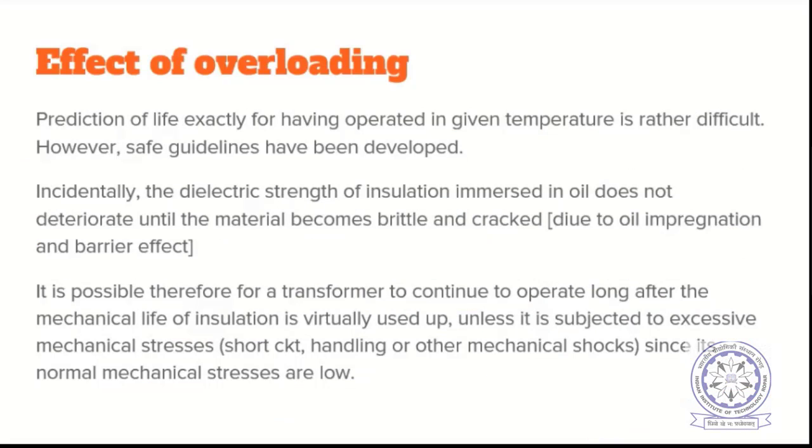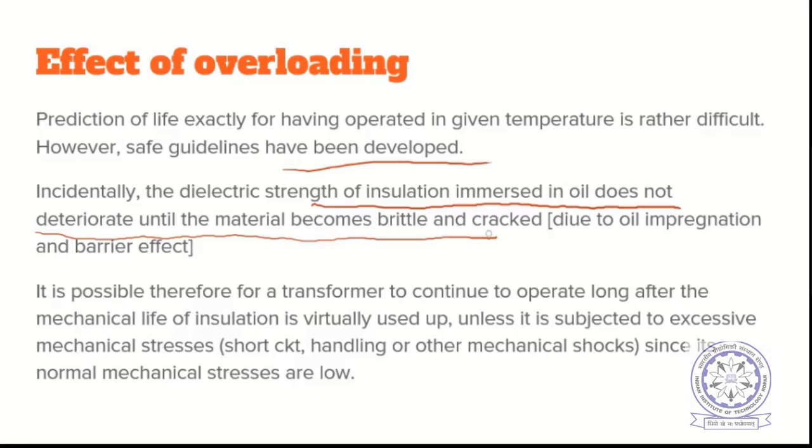Now, predicting life exactly for a given operating temperature is very difficult. But certain guidelines have been developed over a period of time because we have experience of using transformers for a long time. Incidentally, the dielectric strength of insulation immersed in oil does not deteriorate until the material becomes brittle and cracked.